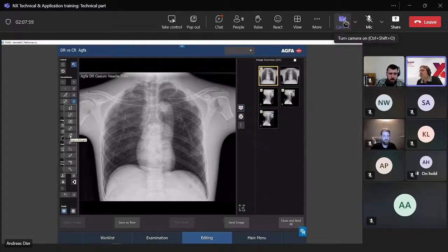Then these two tools: draw a polygon or draw a so-called freehand. The polygon is clear. We have to click the start point and then one point after another. To close it, you have to click on the start point again, and then it is completed. Then we also have the area. The so-called freehand is also some kind of polygon, but it's a rubber line polygon.